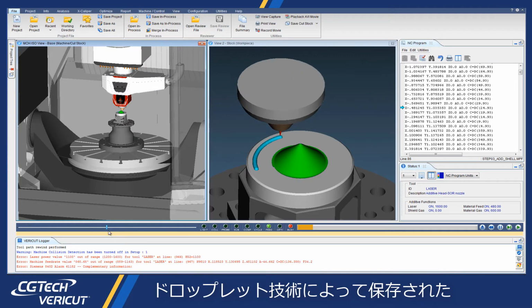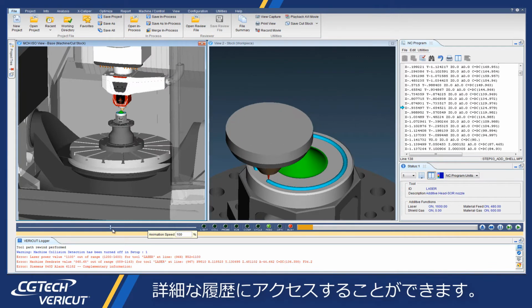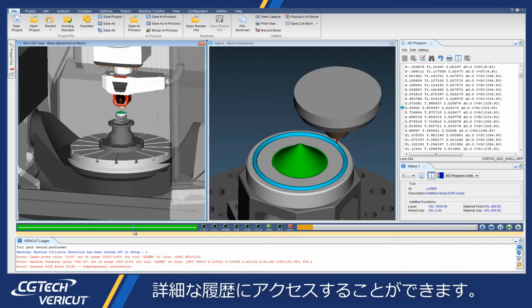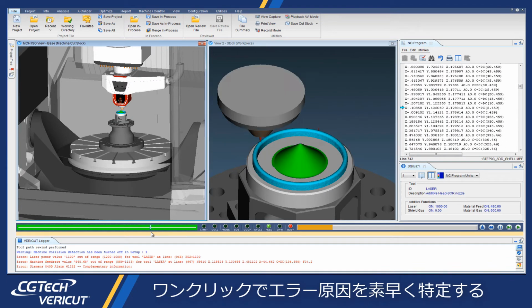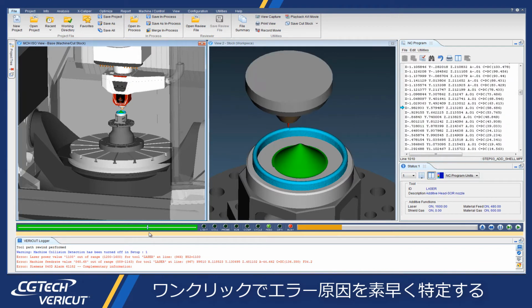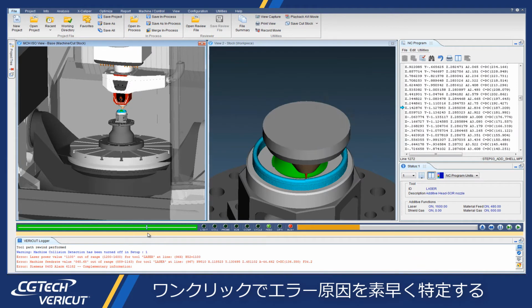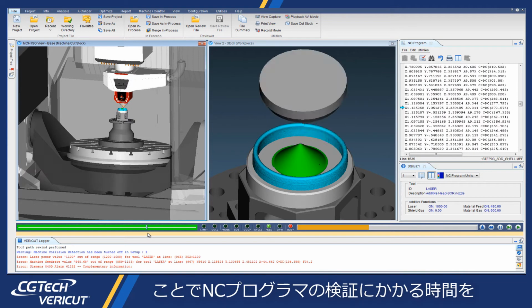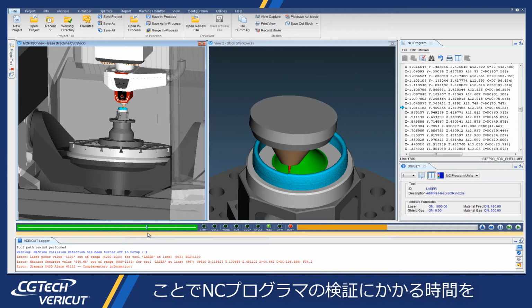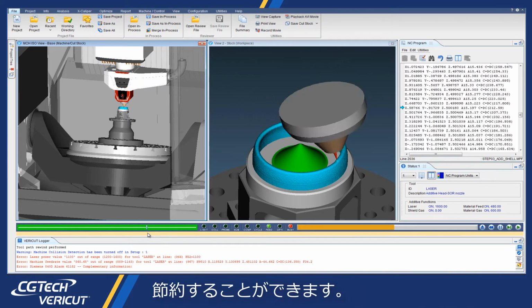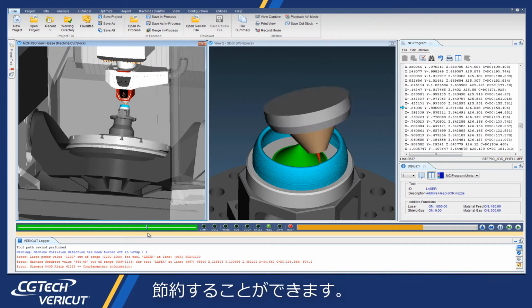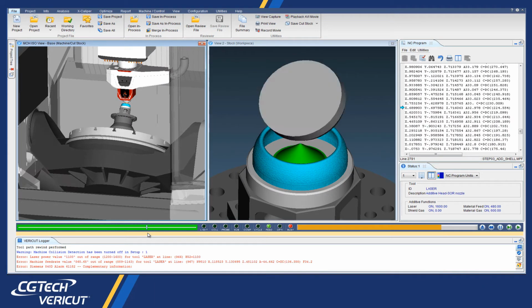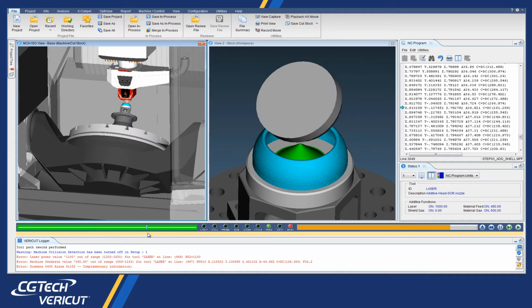This additive capability checks accurate laser cladding and material disposition, detects collision between the machine and the additive part, and finds errors, voids, and misplaced material. For the highest accuracy, Vericut simulates the post-processed NC code that will be used to drive the CNC machine and ensures proper usage of additive manufacturing functions and laser parameters.